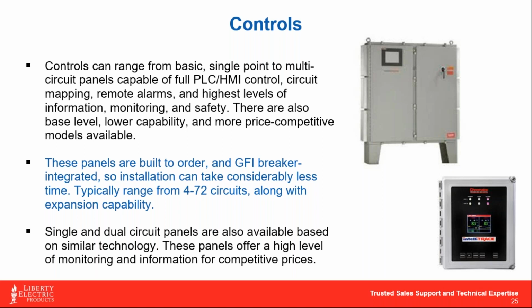We call it circuit mapping, where, let's say you had 24 circuits out there feeding a decent sized tank farm or something, and maybe a third of your circuits are all 2-inch pipes. They're all carrying the same fluid, and literally you could put all 6 or 8 of those pipes together into their own segment, so that when that temperature threshold is hit, it kicks them all on instead of one at a time. But ultimately what I'm trying to tell you is you have all the versatility that you could want in one of these fully integrated panels.